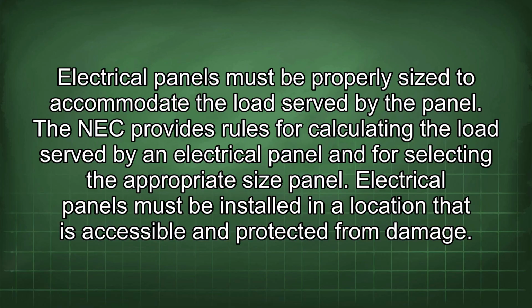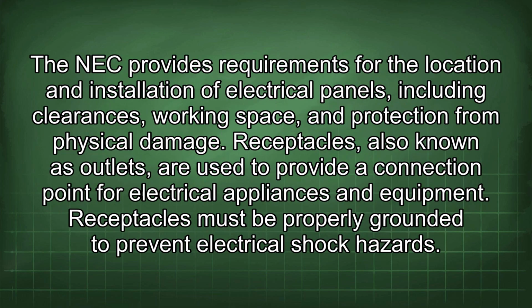Electrical panels must be installed in a location that is accessible and protected from damage. The NEC provides requirements for the location and installation of electrical panels, including clearances, working space, and protection from physical damage.